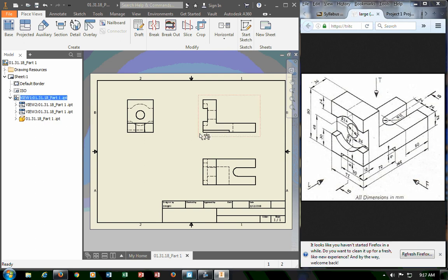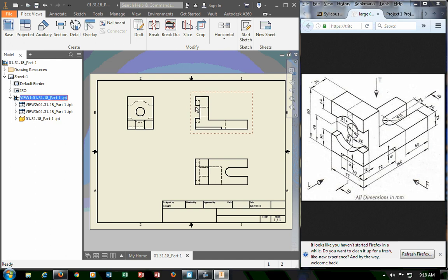The way I know that it did it right is because these 2 points here are not clearly visible here. That entire left side is shown as hidden lines here. That's how I know it was drawn correctly. It's being presented in the correct orientation. What's the other cue? What settings is this particular drawing done to? ISO standards, yes? What's ISO standards? First angle projection. That's why it's correct.